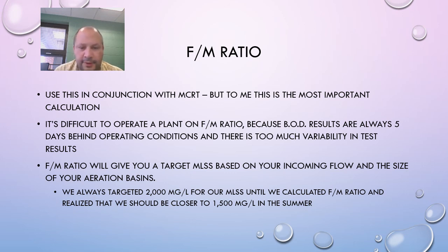Okay, so let's talk about the second formula, which is FM ratio, food to microorganism ratio. As far as practical application, this is something that we would use kind of in conjunction with MCRT to develop a strategy for operating our plant. And the reason that we do that is it's really difficult to run a plant off a constant FM ratio, just because, number one,